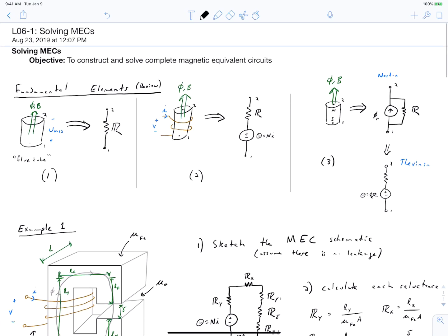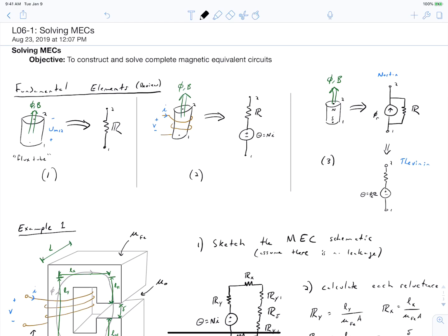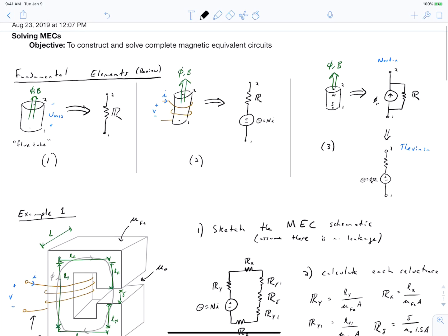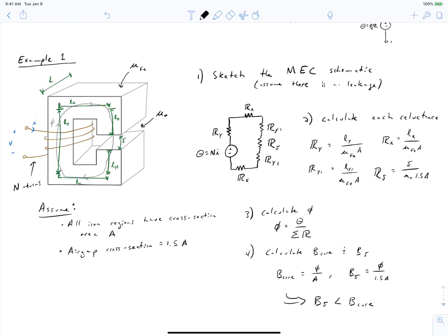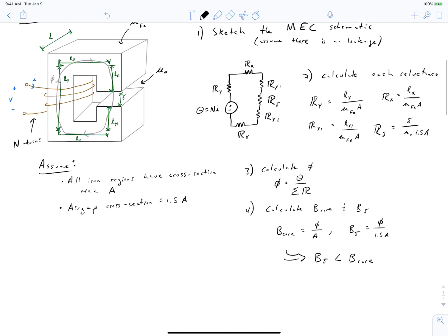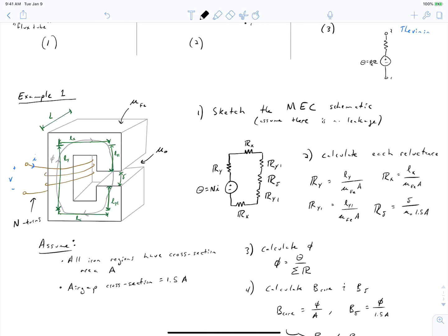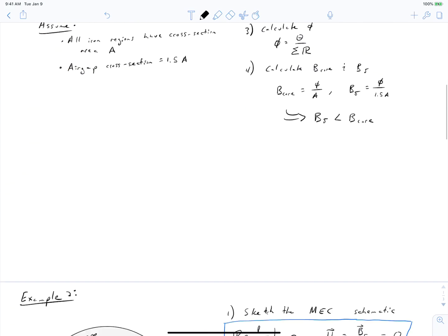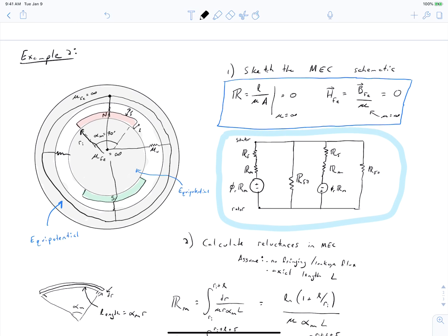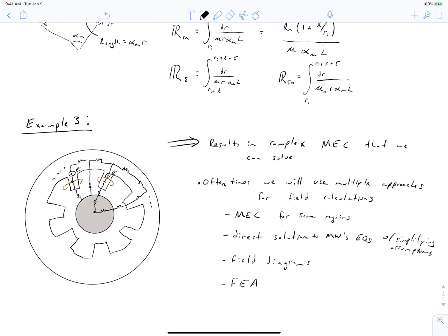In summary, we have been tying the pieces together of magnetic equivalent circuits and showing you how you can use magnetic equivalent circuit elements within a broader reluctance network or flux tube network to solve for magnetic fields at all portions of an electric machine. We've considered both the simple transformer core example or inductor core example, as well as the cross-section of a slotless motor. And finally, we talked about how we could apply these techniques to a general slotted motor.